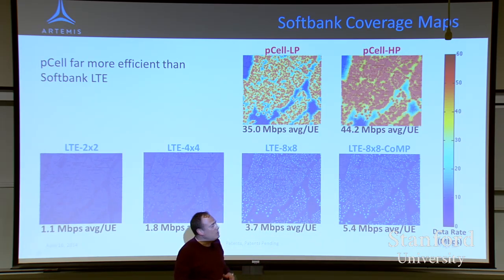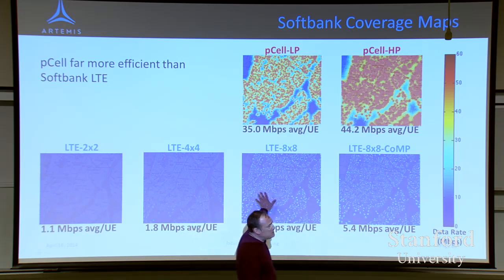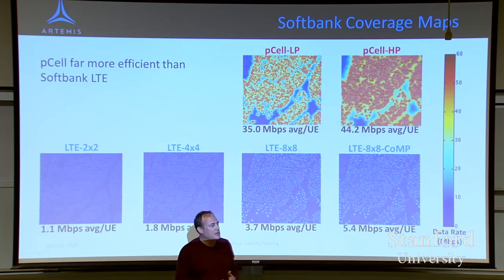The other thing with cooperative multipoint, MIMO's sensitive to motion. Then you add cooperative multipoint, it's very, very sensitive to motion. You're at 2.5 gigahertz. You're talking about people that are not moving, that are on a cell edge, that this really benefits. It's kind of a weird situation. Yes? So these are model numbers as opposed to measured numbers? Model numbers.